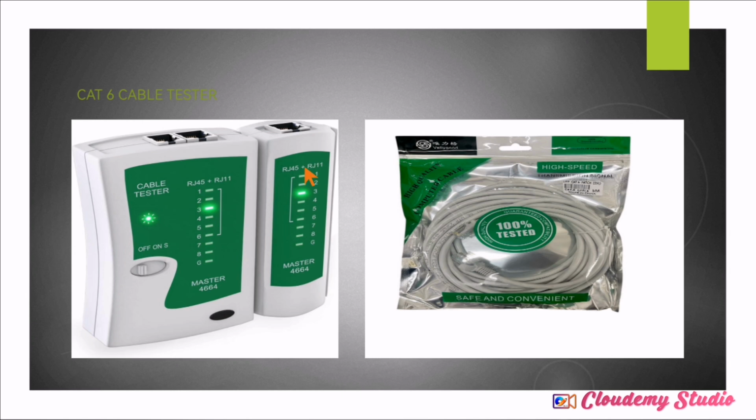So it's the same tool, like I have said. As you can see, this is the tester of Cat6 cable. So I've used 3. If one number here has been skipped, or 2, you'll be able to tell that according to the color code and the number, this cable is not working. So like here we have this 3 and here is 3.